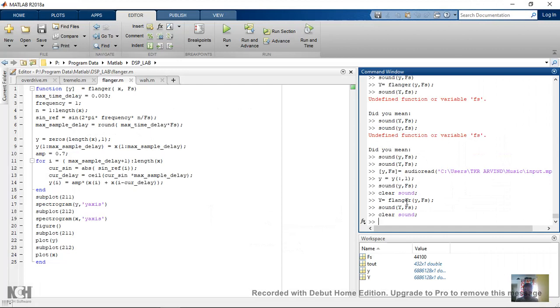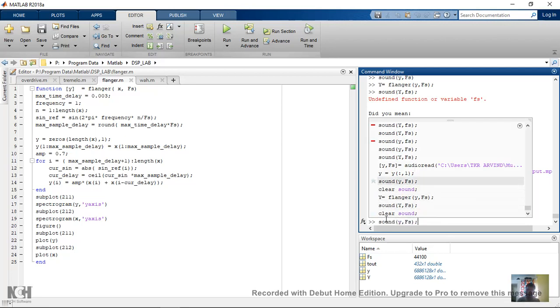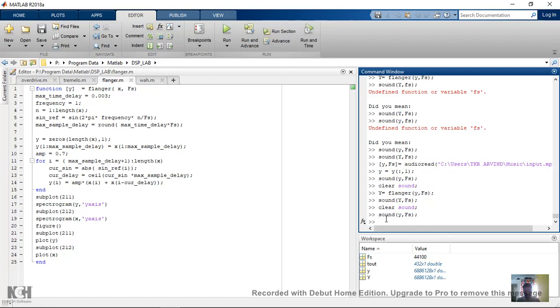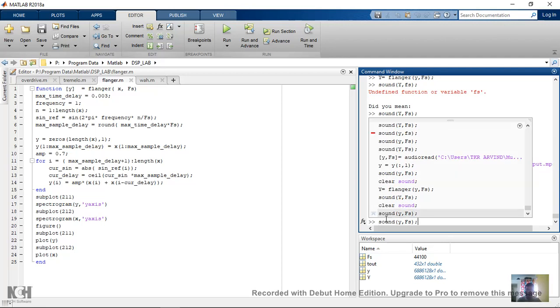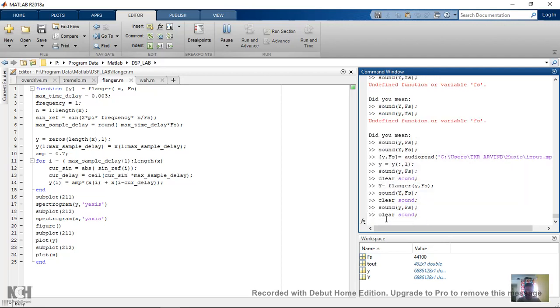So here I have taken a sound as the input, which is read into y. y is the numerical value of the sound, and fs is the sampling frequency, and the sound is read by audioread. Whenever you read an mp3, you will have two columns of sound signal, so I'm taking just one column. So we'll see how the sound looks in the first place. This is the sound that we'll be working on.